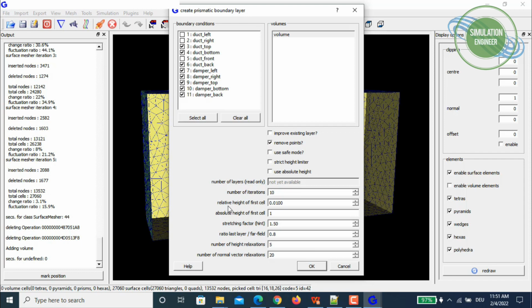If you wanted to have a y plus value of exactly 1, or are doing some specific test cases where you don't want to use a high Reynolds number turbulence model, you should then define not relative but absolute numbers.